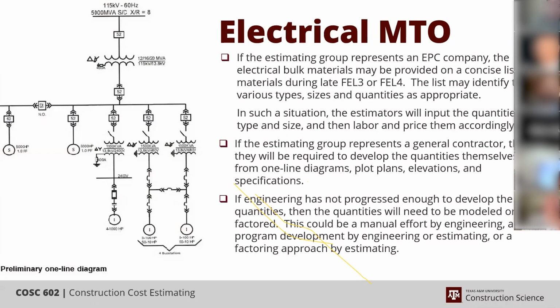The PDC would power the MCC. It wouldn't go to each little bank. You know what I mean? Like the MCC, each motor would have its own little box, its own little bank, and the power would come from the PDC to the MCC as a whole, not to each motor. That's why it's separated out by unit.